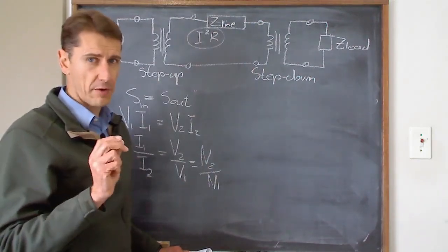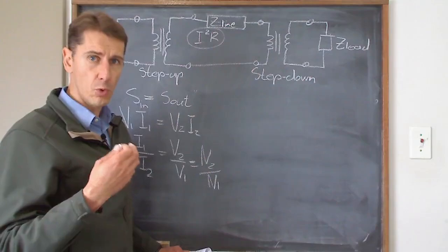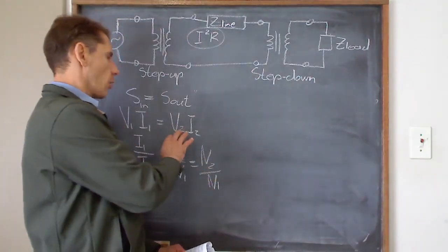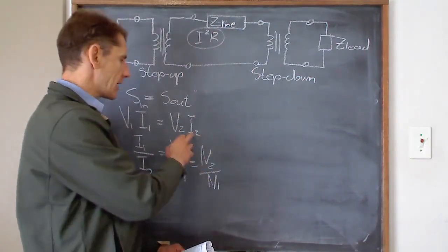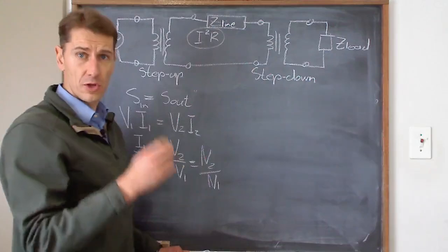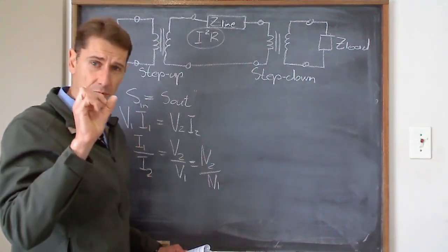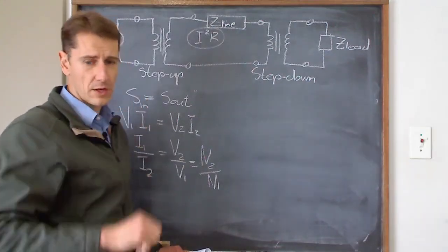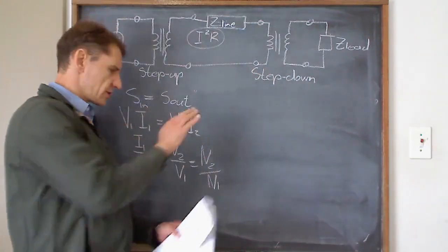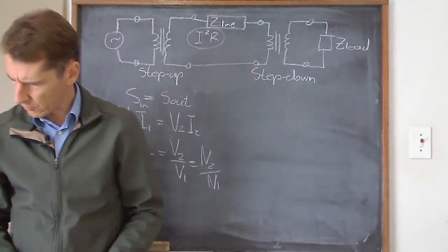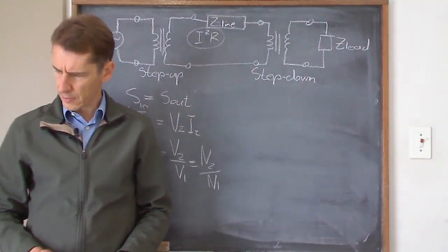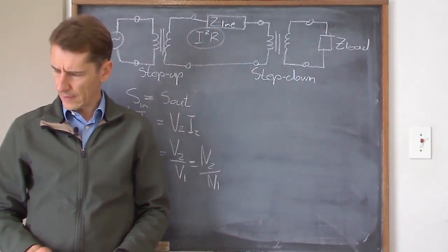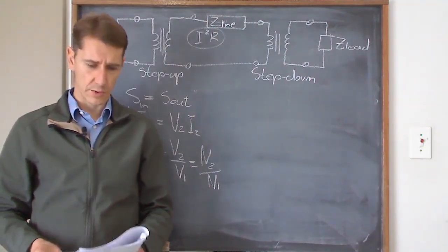If you've got a good power factor, then the majority of it will be watts. But either way, all the VAs have to flow through your transformer. It can only handle so much current through those conductors. So if you want more current, you need thicker conductors. So transformers are always rated in volt amperes. That covers both the current ratio section and the power in ideal transformers in your textbook.